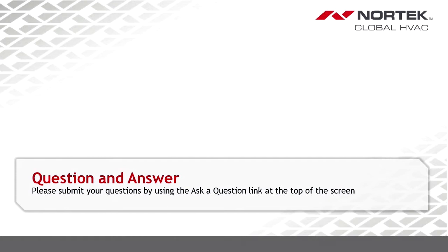Can we balance the refrigerant charge at very low temperatures like 0 degrees? Me personally, if it's a heat pump, I would weigh in that charge when you're down that low. If you want to use this to give you a guide of where you're at on refrigerant charge in those temperatures, it's going to be a little bit iffy there. I'd be taking a lot more readings and doing a lot more checks to verify that refrigerant. We would recommend that you're within normal ranges. 0, I know, is normal.